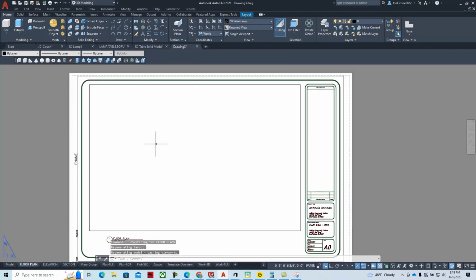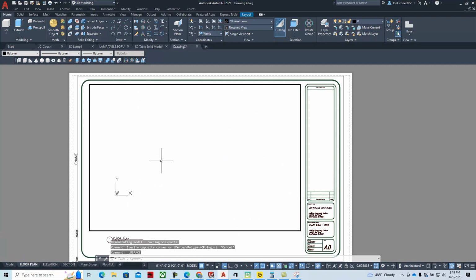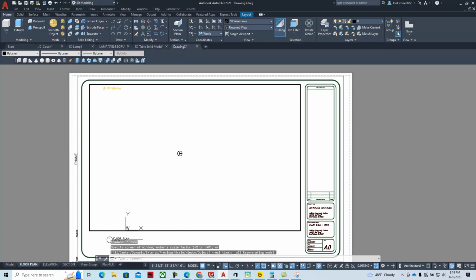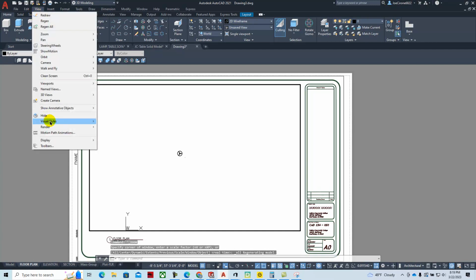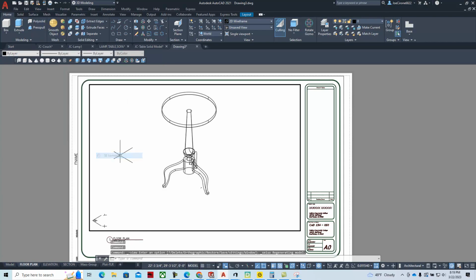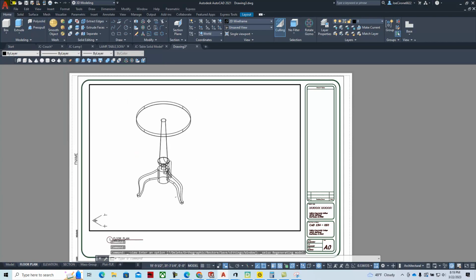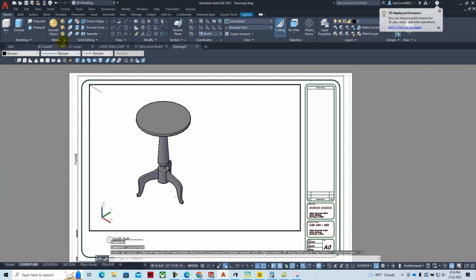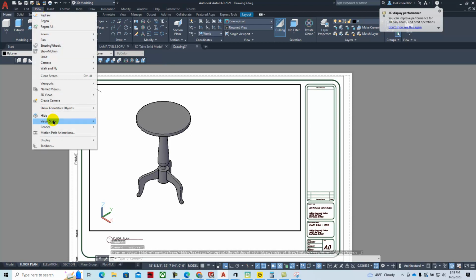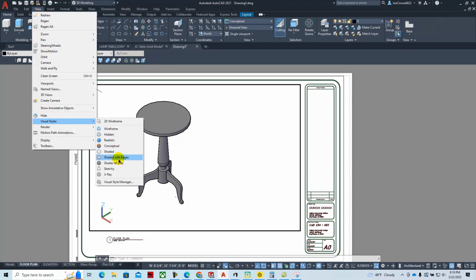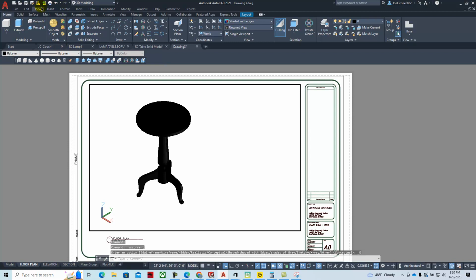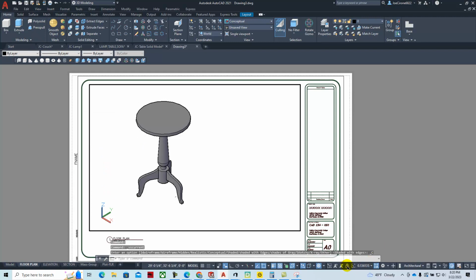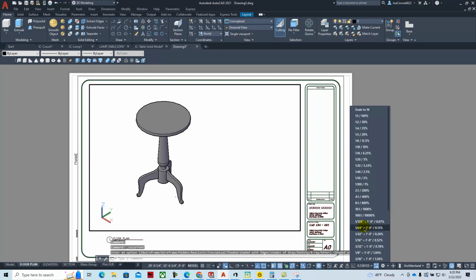We'll go to the floor plan viewport, activate the viewport, view, zoom, all, view, 3D view, southeast isometric, view, visual style, conceptual. You could try some of the other visual styles. I think we'll just leave it with conceptual. Lock in the viewport. Let's see what kind of a scale we can put into that.